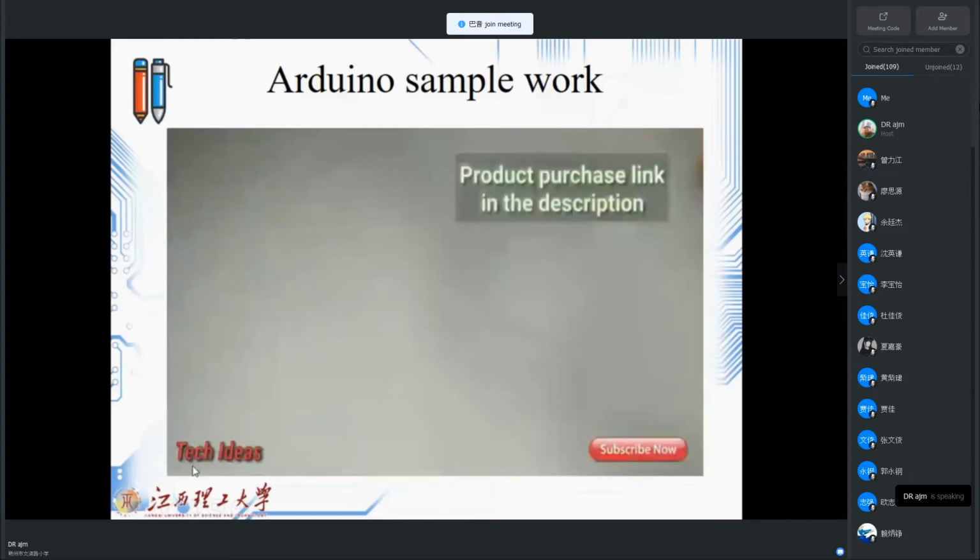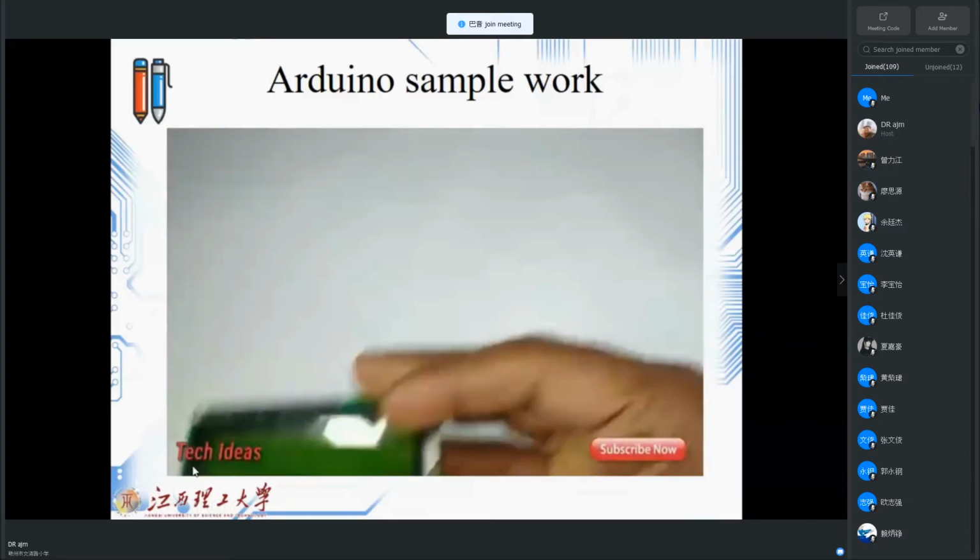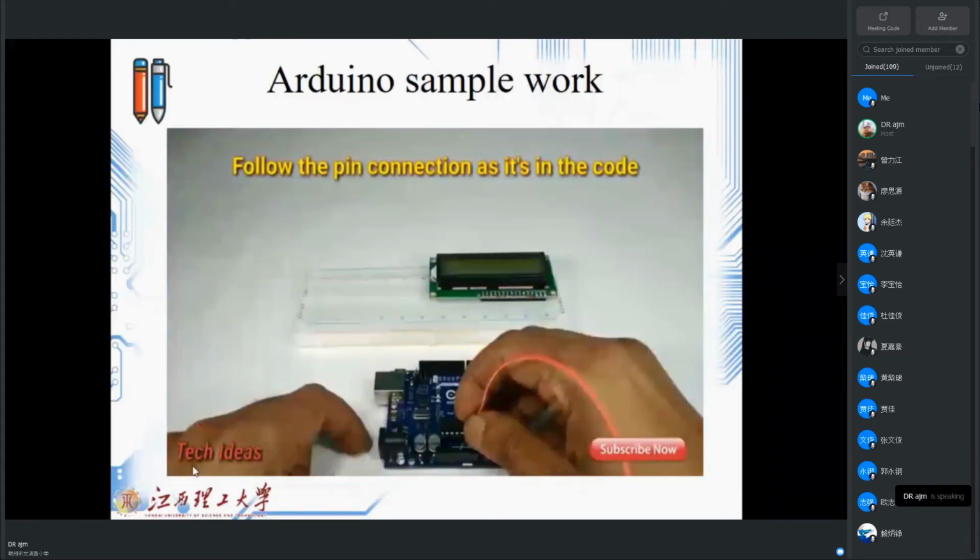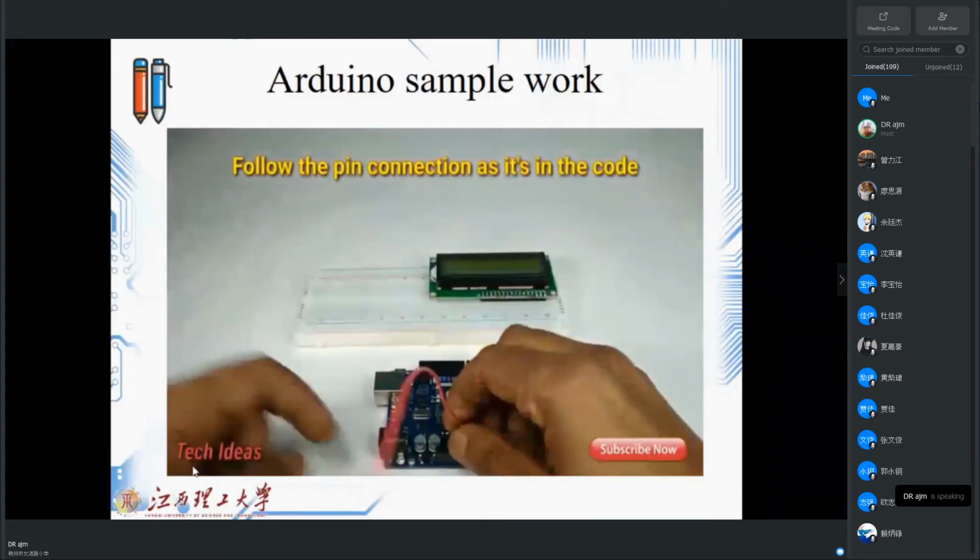And a breadboard. First, we should connect the LCD on the board. Then we should do the wiring with the Uno board. To show the pins, you will see that these pins are specified: first VCC and ground. Then it connects the LCD pins one by one.